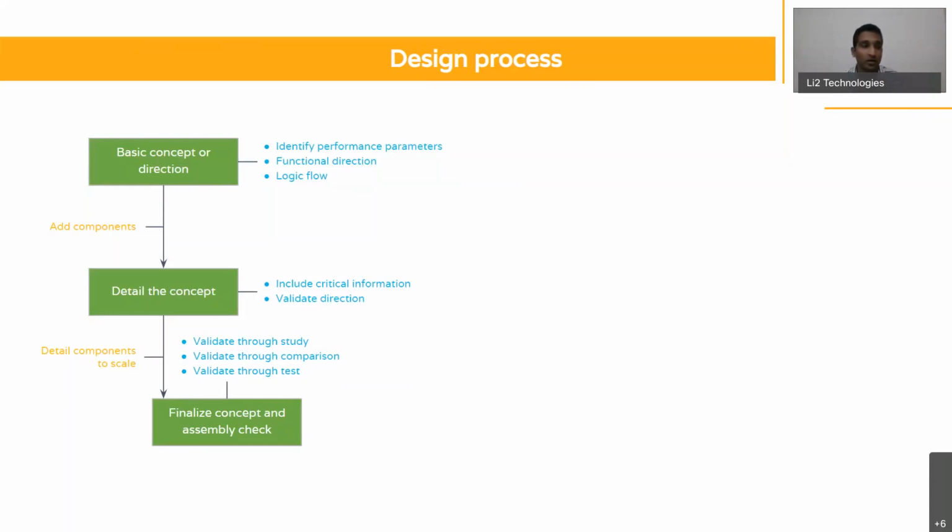So if I'm designing, say, a gearbox, I can compare it to another gearbox that is in the market to see, okay, if that gearbox is working, then my gearbox should work. So you can take these kinds of privileges, and these privileges are necessary because you can't go behind first principles on every aspect of design, because it takes a lot of time. But you can be a bit smart in terms of saying, let me actually take this direction because this is already available, this is already working in the market, so my design should work. And then add your elements to that design that adds better features or anything else.